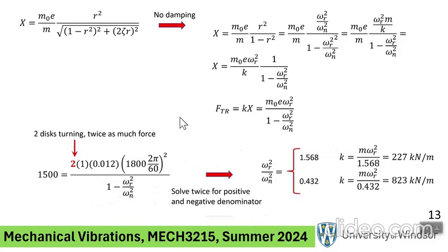okay? In reality, you see that denominator, that 1 minus r squared? This is a bad way of writing it. It should be absolute value of 1 minus r squared. You see that? When you take the square root of 1 minus r squared squared, that is not 1 minus r squared. It is the absolute value of 1 minus r squared. That's why we're getting two solutions.